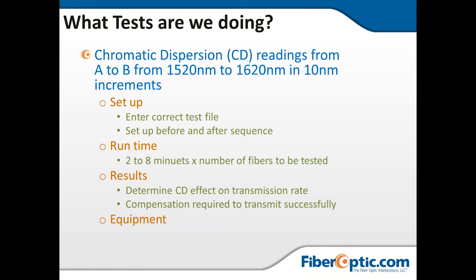If we overcompensate, we're going to distort the image by crunching it too much, and we're going to ultimately get four-wave mixing and other issues that will then cause us to fail. So getting that measured chromatic dispersion to confirm our engineering is absolutely critical to making sure your plant works today, tomorrow, 10 years down the road, at the wavelength you're trying to operate and the bandwidth.